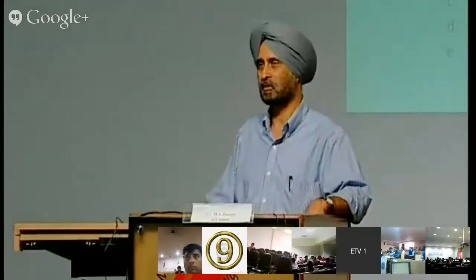This circuit was made in a 180 nanometer process, twin well process with single gate and single Vt. All transistors used in this have a single threshold voltage. It has 4 level metal, a 4 metal process, and we have made this circuit at SCL here in Chandigarh, and we have tested this also. I will show you the results of this.